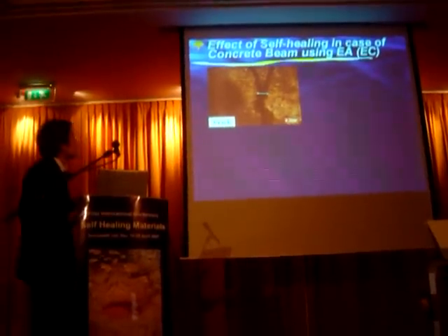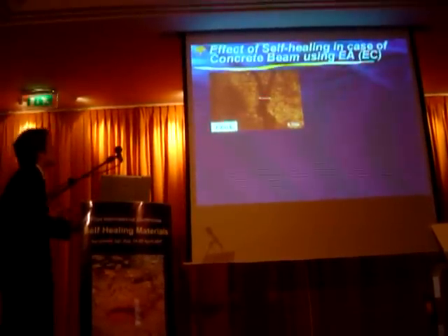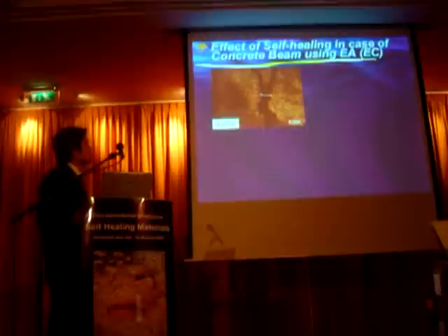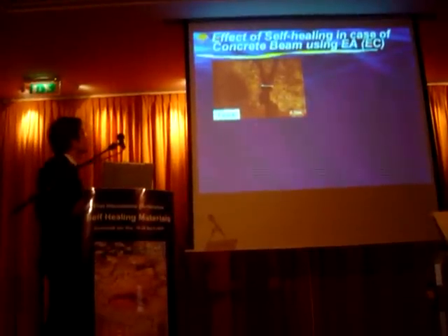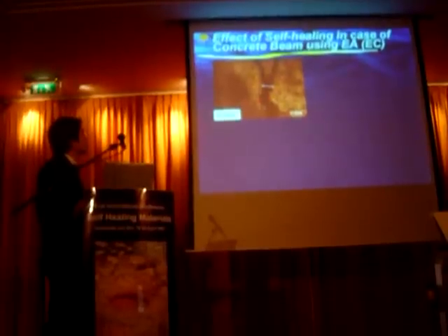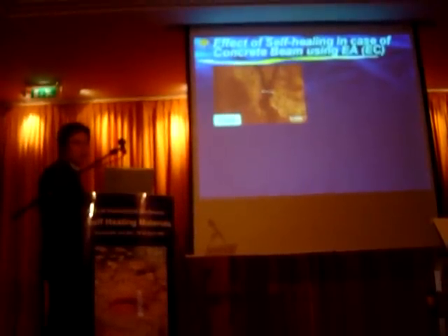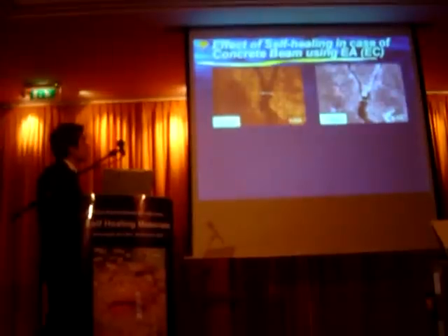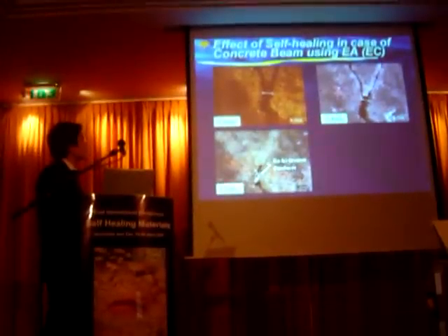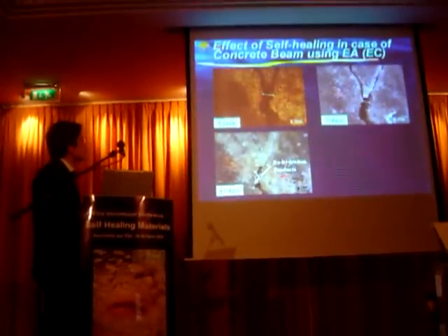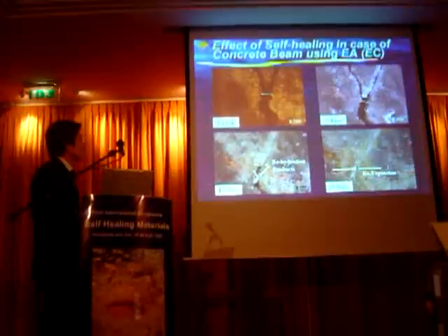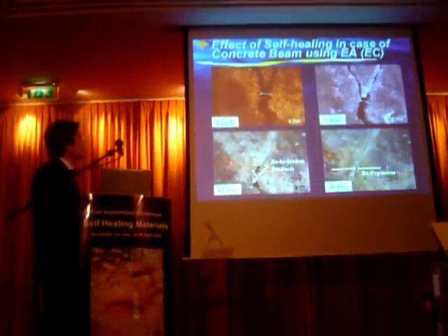This figure shows the impact of self-healing in the case of the concrete beam using expansive agent. You can see that its initial crack was 0.22 millimeters. After water supply, the crack was healed by rehydration products and re-expansion until 28 days.